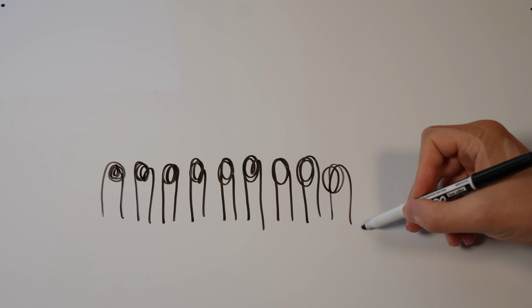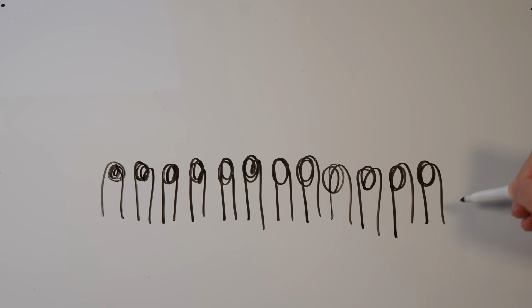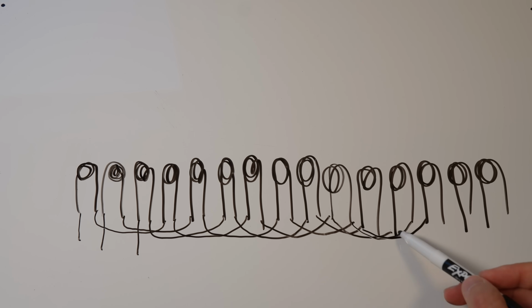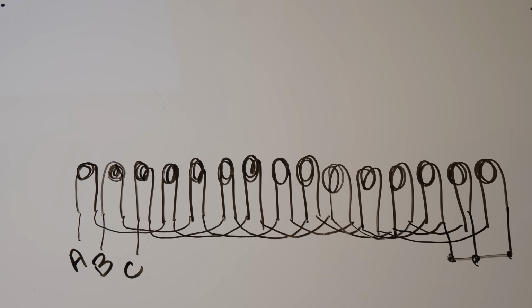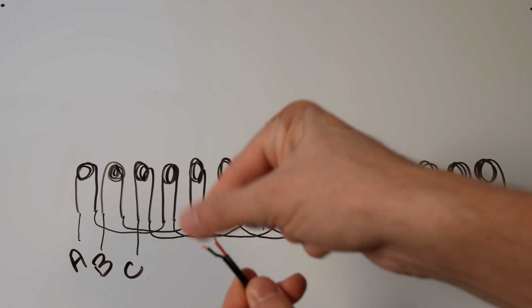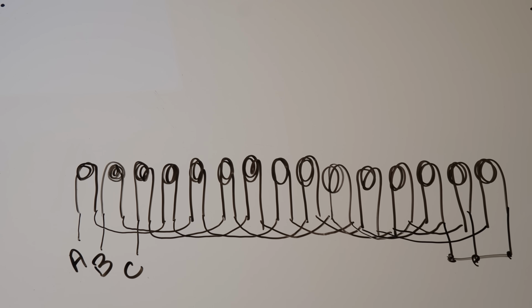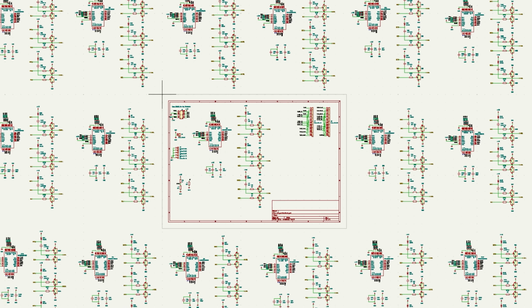If you're wondering why I need the ability to enable and disable coil segments, well, remember how I said I'm overdriving these coils? This means I want to avoid powering coils that are too far ahead or behind the train, and thus not helping accelerate it forwards. This launch section has nearly 100 coils, so if I tried powering all of them in sync, I'd run into serious power limitations and risk overheating. Alternatively, controlling each coil individually would require a huge number of electronic components and a lot of microcontroller pins to control them all.